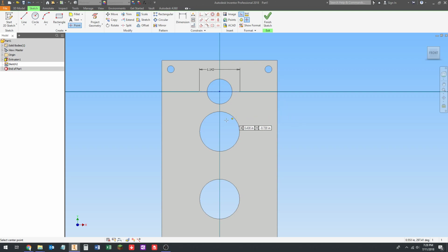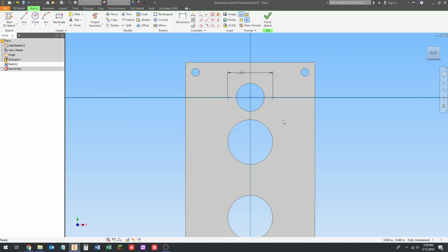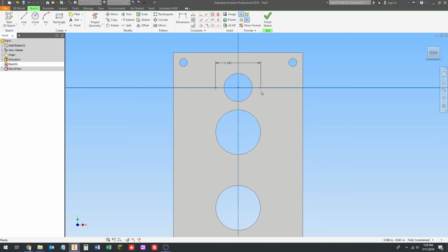So we're going to click. We're going to find the end point highlighted by the green dot. We're going to click. And we're going to go to the other end and place another one down here by clicking. Okay, I'm going to get out of that tool by pressing escape. So now we can see, they're hard to see, but there's two little dotted crosses. Those represent where the center of the hole is. So they're attached to the endpoints of that line, so we're done here.